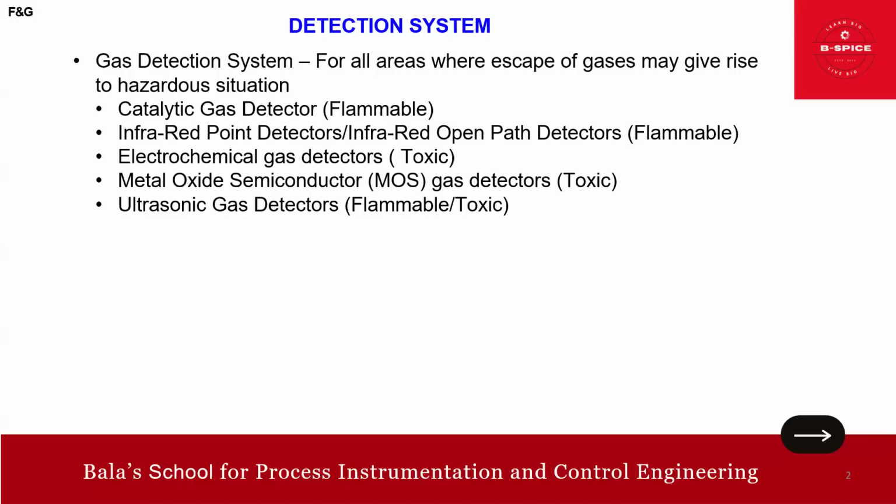Then here one advantage also I want to inform you. No gas contact needed. Unlike other gas detectors, the ultrasonic detector does not need to come in contact with the gas because it detects the sound of the gas escaping, making it effective even in windy or ventilated environments. So that is the point we need to take note of. Apart from that, it provides real-time detection, friends, allowing for immediate response to potential hazards.